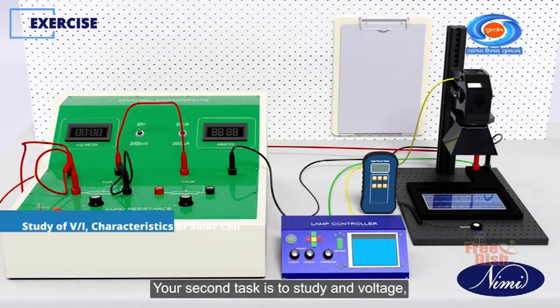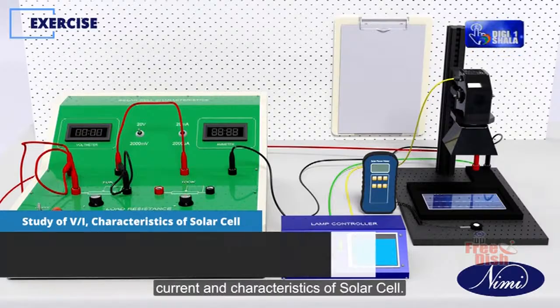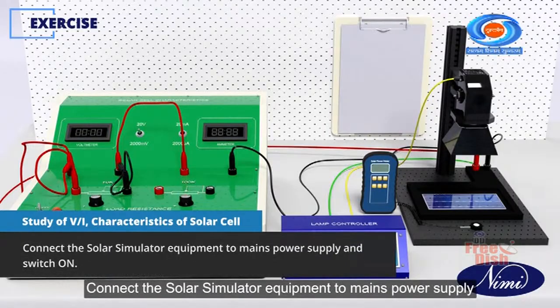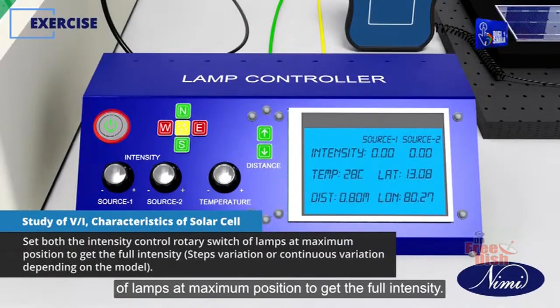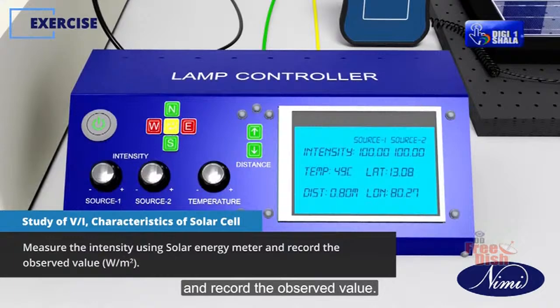Your second task is to study voltage, current and characteristics of a solar cell. To perform this task, you need a solar simulation lab. Connect the solar simulator equipment to the mains power supply and switch on. Set both the intensity control rotary switches of the lamps at maximum position to get the full intensity. Measure the intensity using the solar energy meter and record the observed value.